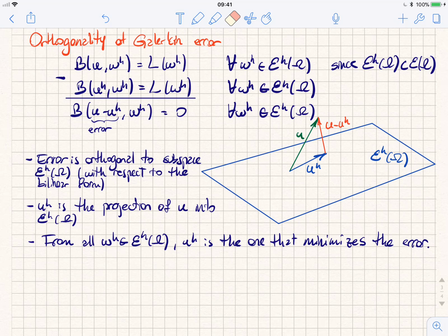So let's say you are doing dynamics and you want to get modes of vibration for a beam, for example, and then you take some Fourier series basis functions, and then you can use those basis functions in your entire bar, and it's still a finite dimensional space. You end up with a system of linear equations to solve. In fact, for dynamics you end up with an eigenvalue problem to get the eigenshapes and so on. But those functions are acting globally, and that is not what we want.